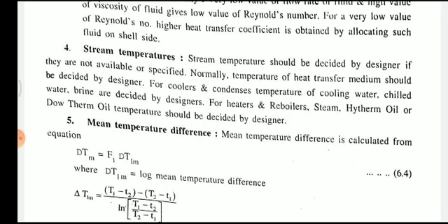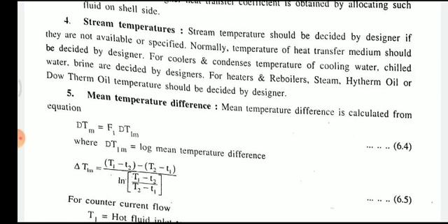If they are not available or specified, normally the temperature of the heat transfer medium should be decided by the designer. For coolers and condensers, the temperature of cooling water, chilled water, brine are decided by the designer as per the application of the heat exchanger.